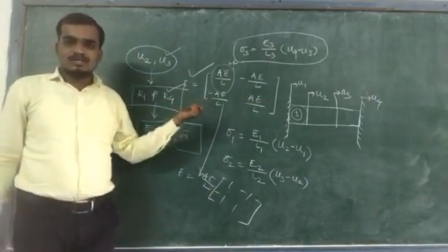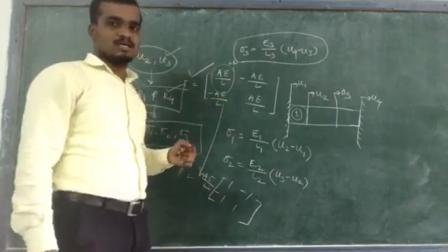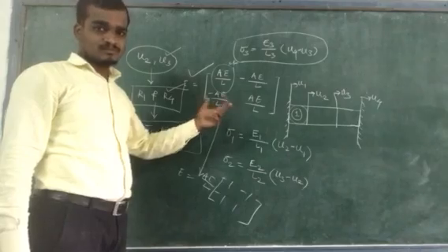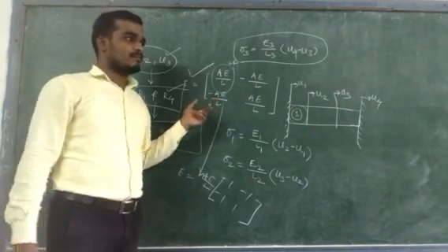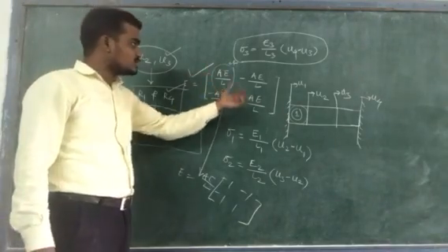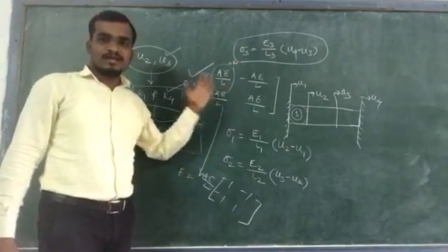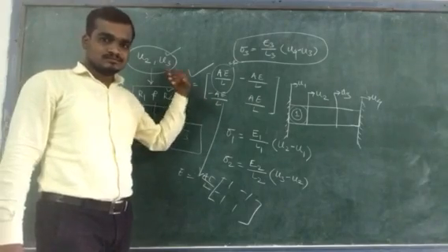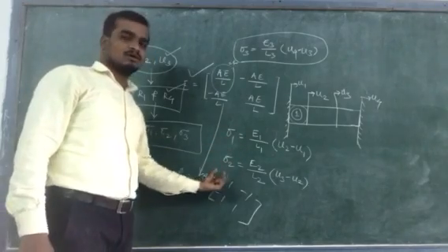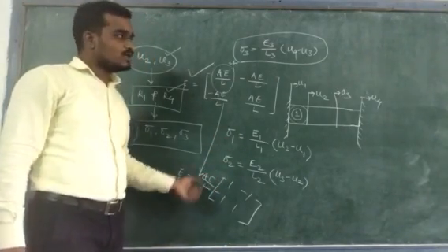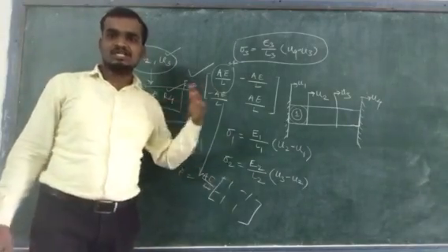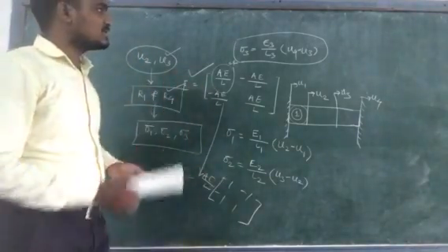The next step is to apply the elimination approach to get the displacement values first. By applying the elimination approach, you will get the remaining 2 or 3 equations. By using these equations, you will get the displacement values. And finally, by using the displacement values, you will get the forces or reactions, and also the stress values, sigma 1, sigma 2 and sigma 3. In this way, you can proceed to get the values of stresses in each element.